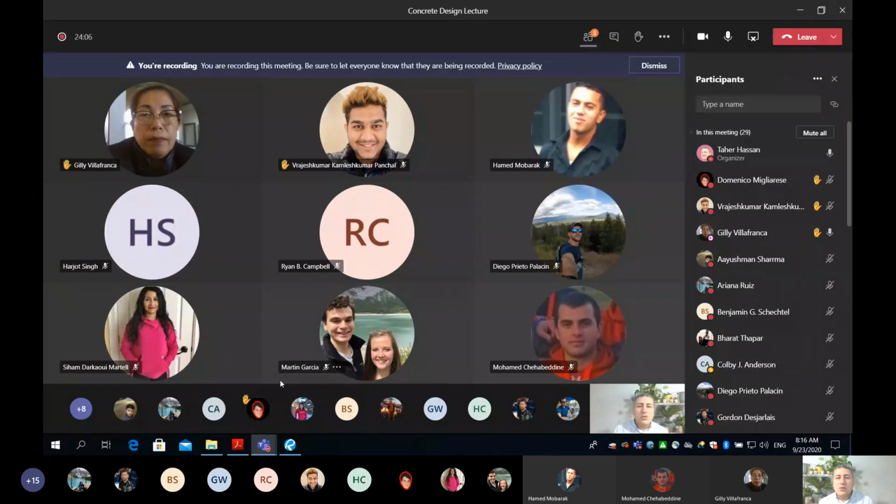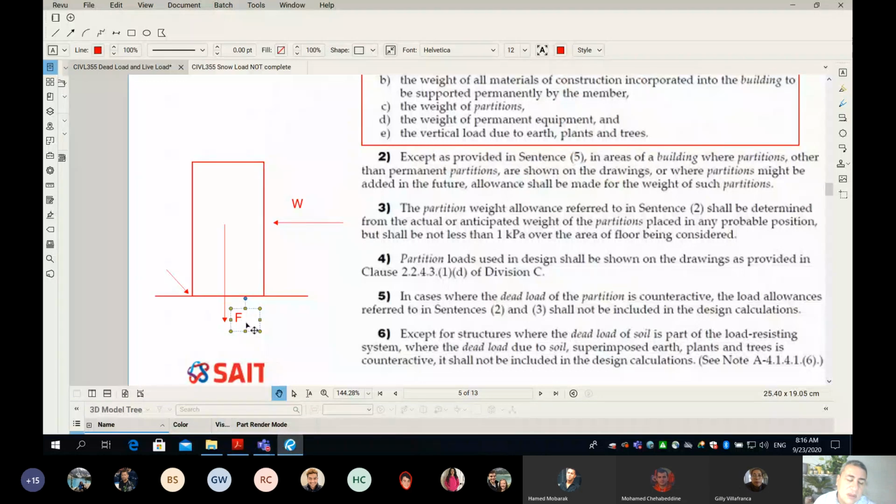So that's true, guys. When we think about load, like the force F, you shouldn't include the snow, because the snow is counteractive and there is no guarantee that the snow will stay. Sometimes we have a storm, like a windstorm, and we don't have any snow, which means it is not really in our best interest to ask the snow to help us stabilize our building. Next, should I use the live load in the calculations of force F? Please show your hands.